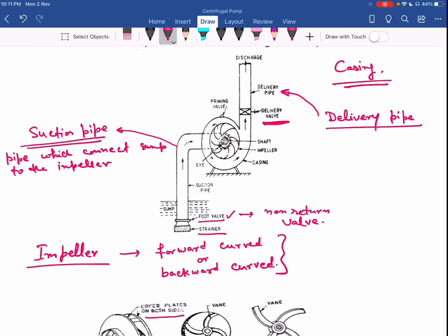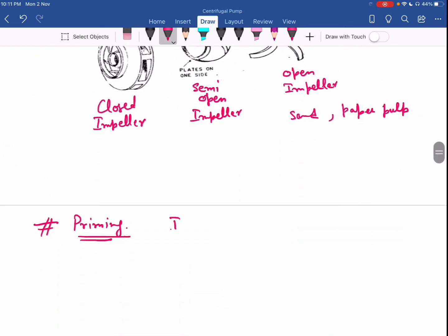As long as the impeller rotates in the air, the centrifugal head developed by this forced vortex will be proportional to the density of air. So within my impeller there is only air, and whatever pressure is produced depends on the density of air.